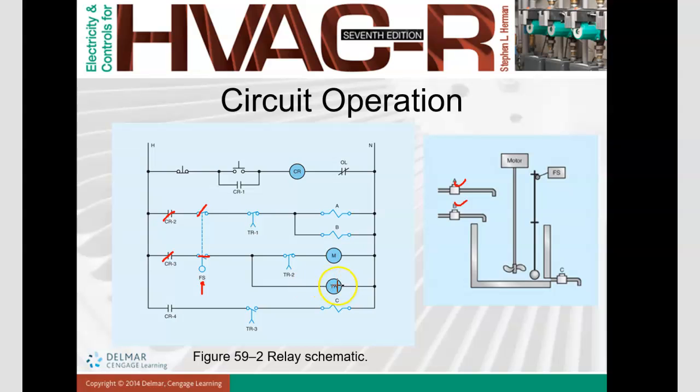So when it energizes, what happens? It will send signal towards time relay number 1, time relay number 2, contactor, time relay number 3. From normally open become close, from normally close become open. So what happened? This one will be open. This one will be open. And this one will be closed. Okay, after 1 minute. So this one open means this is safety actually.